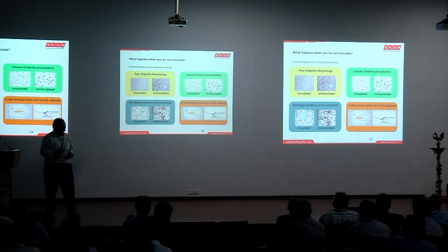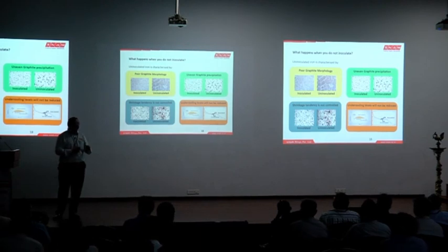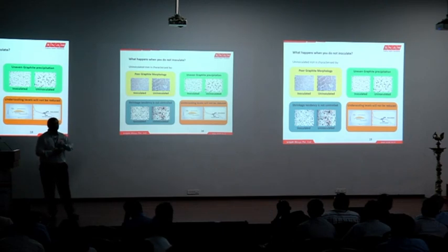So can I produce cast iron without inoculation? Yes, possible. But the problem is you will be lacking uniformity. It does not mean that if you don't add inoculant, you end up with 100% carbides. No. Your liquid metal by itself will have around 50 to 60% of the potency to produce enough graphitization. The problem is because of varying section thickness, because of the cooling rate, and because of the profile of the casting, the same carbon equivalent works a different way at different locations.